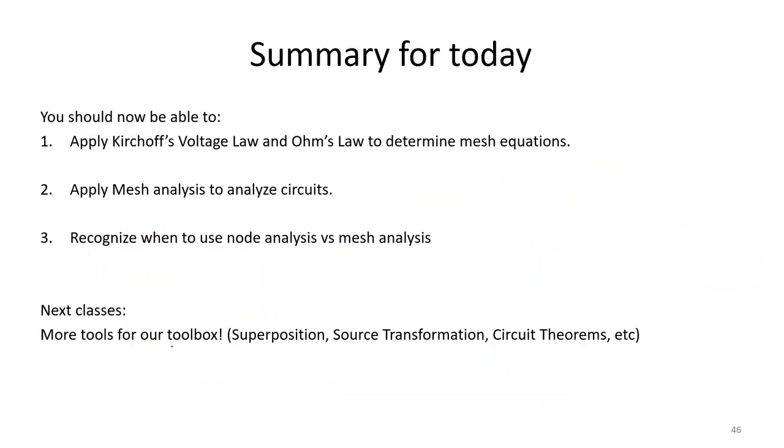All right, so thanks everyone for joining the fun today. Hopefully now you're more comfortable with applying Kirchhoff's voltage law and Ohm's law to determine mesh equations. You should see that mesh analysis is a really powerful tool, and we will continue to use it. So make sure you start practicing applying mesh analysis to analyze circuits. And finally, keep an eye out for when you want to use node analysis versus mesh analysis. Remember, for circuits that contain very few nodes, node analysis might be easier. If your circuit contains very few meshes, then mesh analysis might be easier.